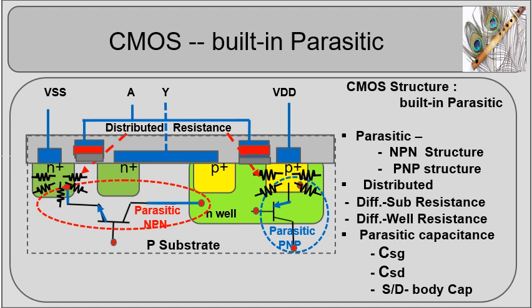In a CMOS structure, P and N MOSFETs are mounted, one in a well and the other in the substrate. The CMOS structure has built-in parasitic elements like BJTs created by source, channel and drain layers. Overlapping and reverse biased well and substrate-like layers form PN junctions.